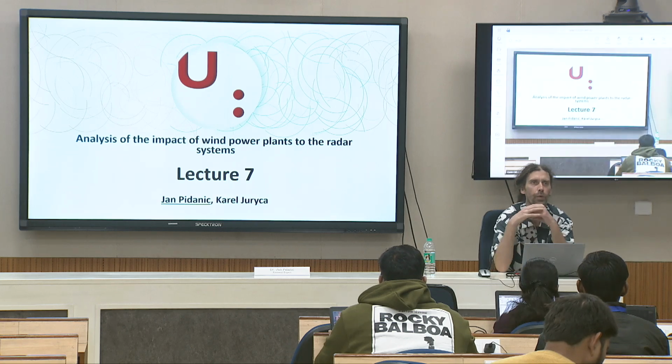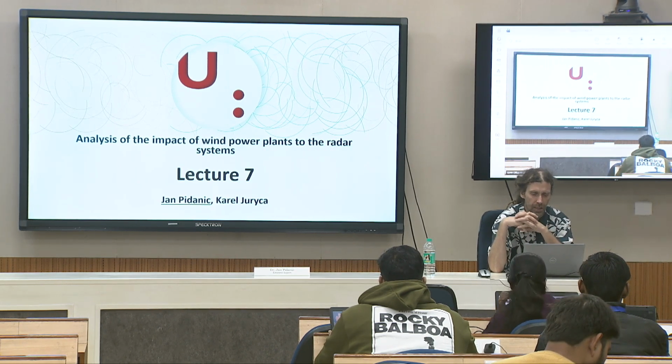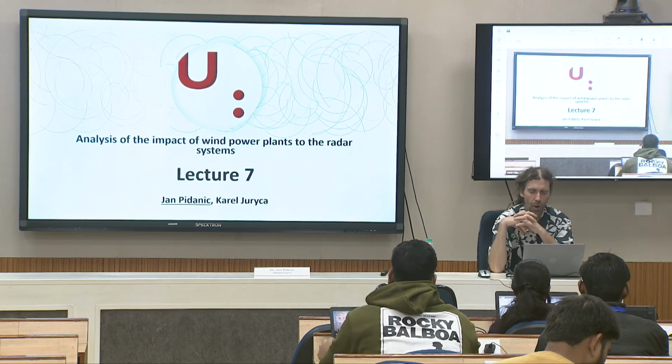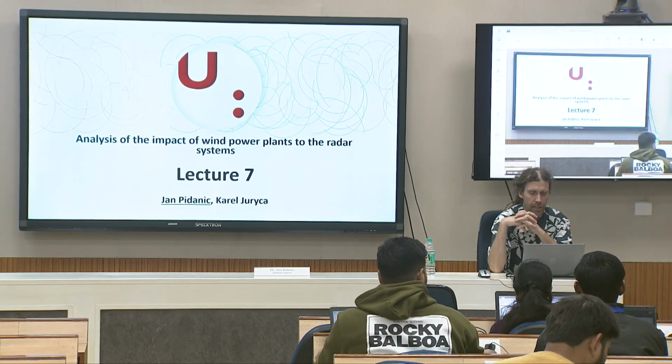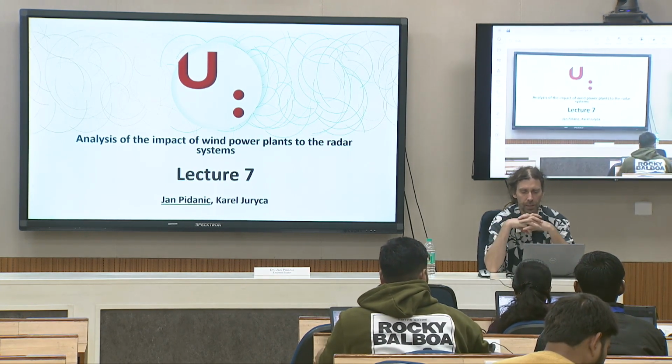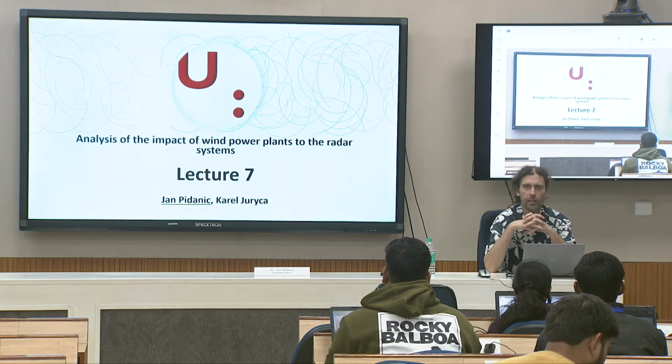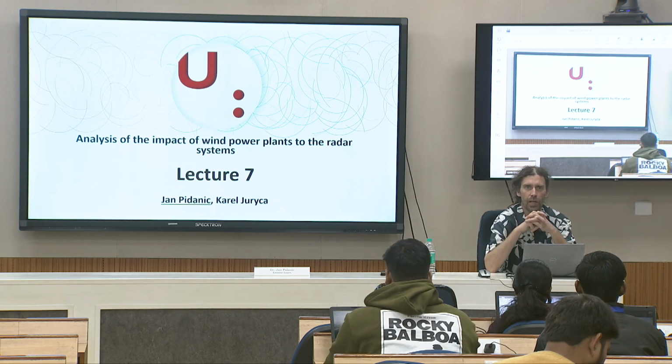Up to now, we could see that wind turbines create complex Doppler clutter, and how we can simulate and measure this clutter. So in this lecture we will have only one goal: given such data, how can we suppress the wind turbine component without damaging real targets?